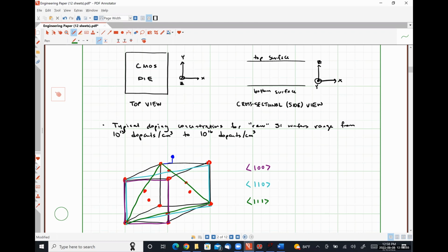Okay. These different surfaces have different electrical and mechanical properties, and so are used for different types of things, depending on what we're looking for. So for electronics, it's overwhelmingly the 100 plane, sometimes the 110 planes that get used. For microelectromechanical systems, it depends on what shape it is that we're trying to pattern in our silicon as to what plane we're going to use.